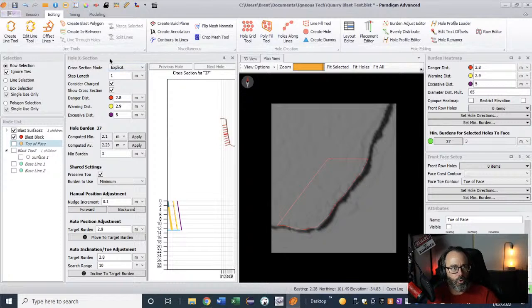Here we're going to use the Whole X Section tool, which is in Paradigm. We'll see this update when I actually put some blast holes in. This is giving me a section for an old hole, but it gives you a sectional view and gives you minimum distances, and you can set the step length from 1 meter to 0.5 or to whatever your issue is. Maybe you do your design based on bore track rod length. Well, then your rod length might be a 2 meter rod length, so maybe that's the interval you need, the step length.